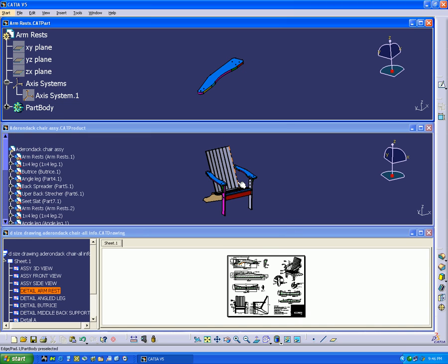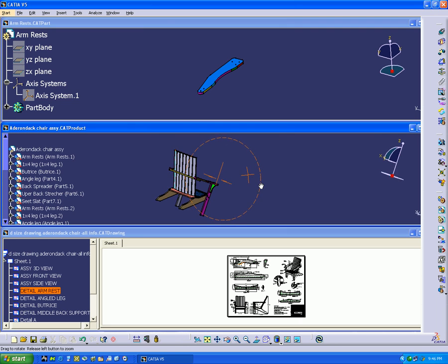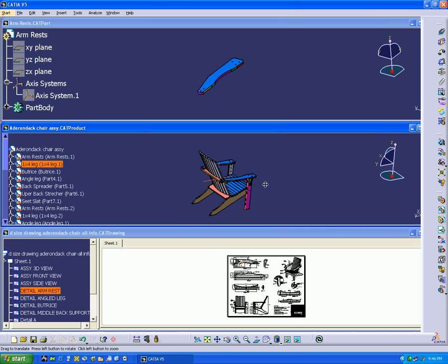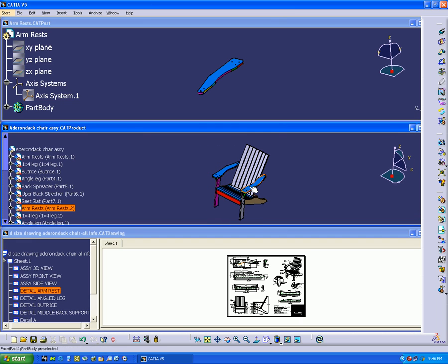There's many more part files associated with this, for example, these legs here, and these slats for the seat area and the back of the seat. There's also more parts in the back here, and typically I don't model fasteners. I'll just call them out on the material list of the drawing down in here, and then I'll have the fastener locations on the isometric view of the drawing.